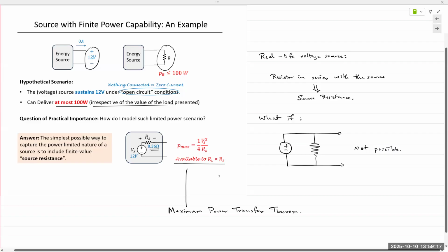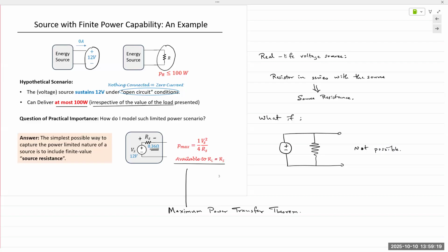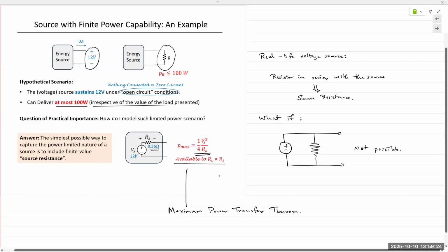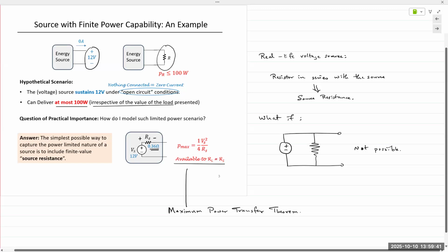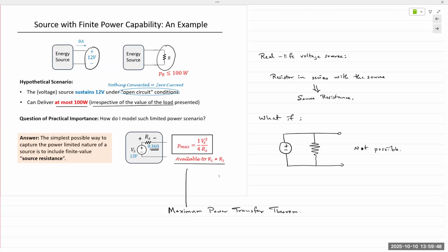And when we derive it by again applying Ohm's law in that circuit, then maximum power comes out to this value. P is equal to V squared over R. V in this case is Vs. R is a series combination of Rs and RL. In order for maximum power to be transferred, we set the circuit conditions and calculate Pmax as 1/4 of V squared over R.